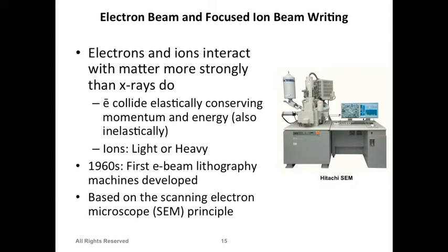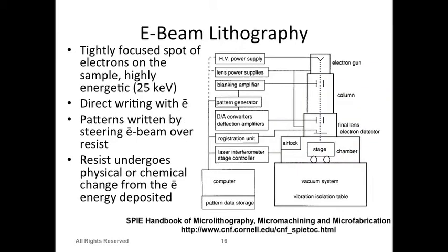So in a regular E-beam lithography, you use a focused beam with high energy, 5 to 25, 30 kilo electron volts. There's a wafer here where you can control the stage, moving it left and right, up and down, and that focused electron beam works as your pen, an electron pen, where you can write on the surface. You can generate any pattern in the software attached to the electron beam controller. Then whatever pattern you feed it, it will just start writing accordingly.